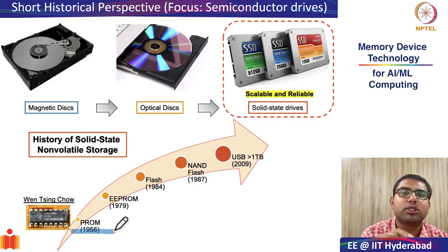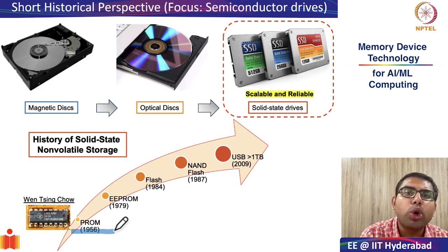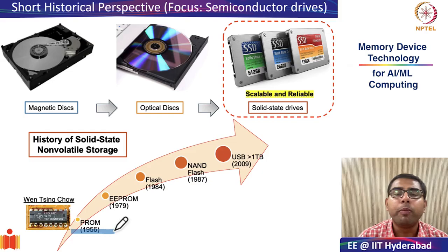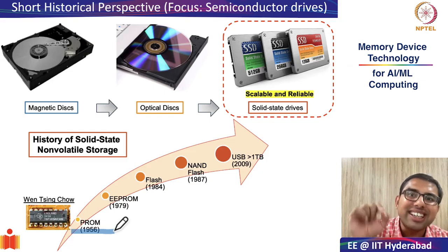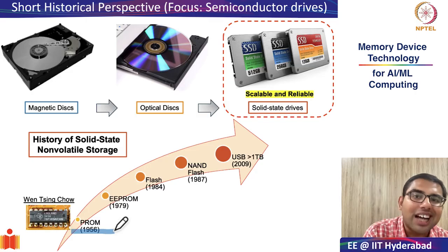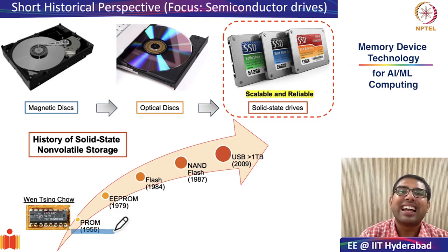These could be metal insulator metal junctions also. In these cases, at the beginning, all the array elements are pre-coded to 1 because everything is working. Then only onto certain bits, you pass a large current and you make the fuse blow up. Therefore, the 1 becomes a 0. This can only be done once, and therefore it was called a programmable read-only memory. Once you burn the fuse, the data is permanent.